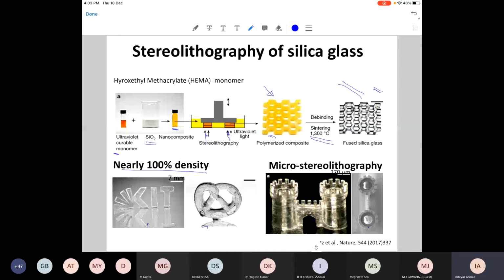So a similar slurry is actually prepared and extruded through a nozzle here, and you can actually build layers on it, inscribe on the surface, and you can control the XY table on which you are depositing the product, and you can make any shape you want.